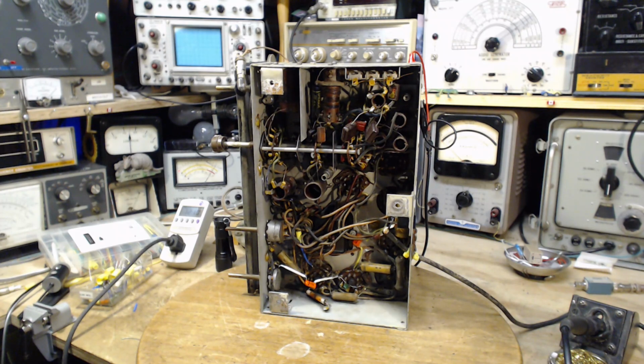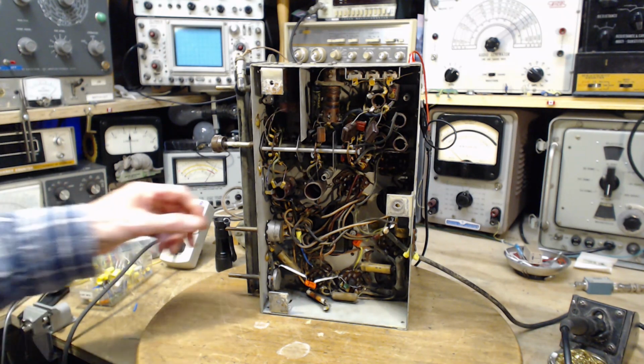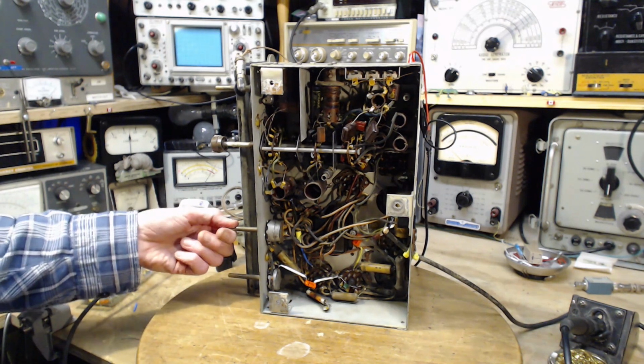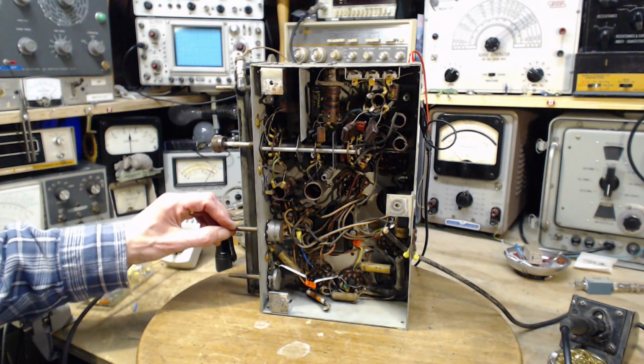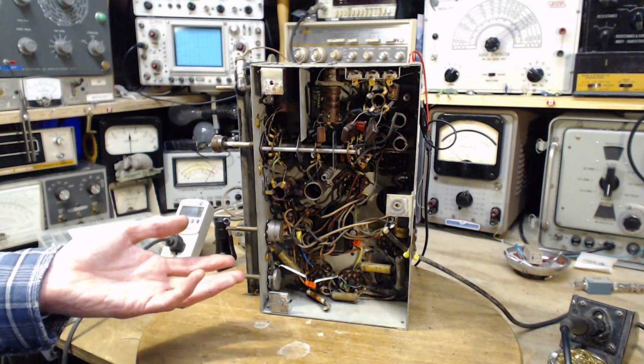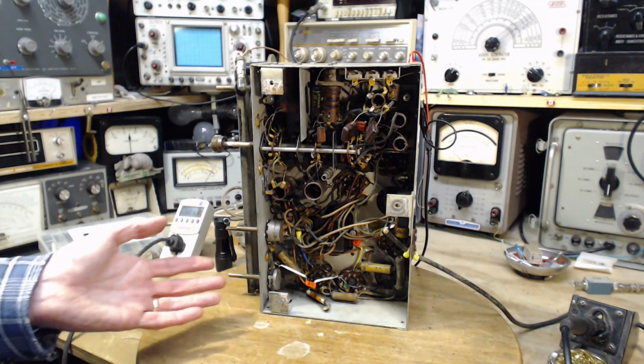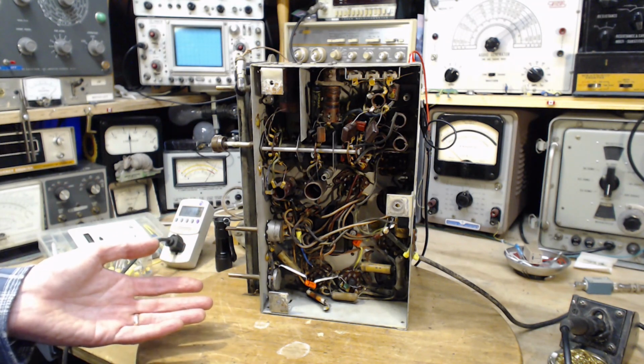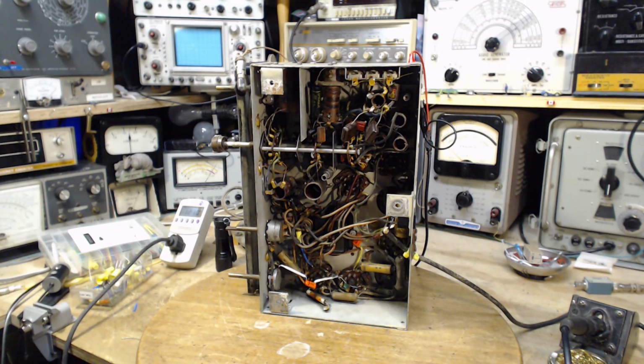Now later on we might discover that in fact I'm right about the earlier stages of the radio suppressing the treble part of the signal, and then me compensating for it in the audio stages with this unnecessarily or unwisely small capacitor. Well, in thinking about that, the tone control can cut treble off, so I can tone it out if there's too much treble after I align the radio, which I don't think is going to happen. But if it did, there's only so much treble in the radio signal, and then they cut it off, at 5 kilohertz, I think. No more than that. Okay, that's it for today.